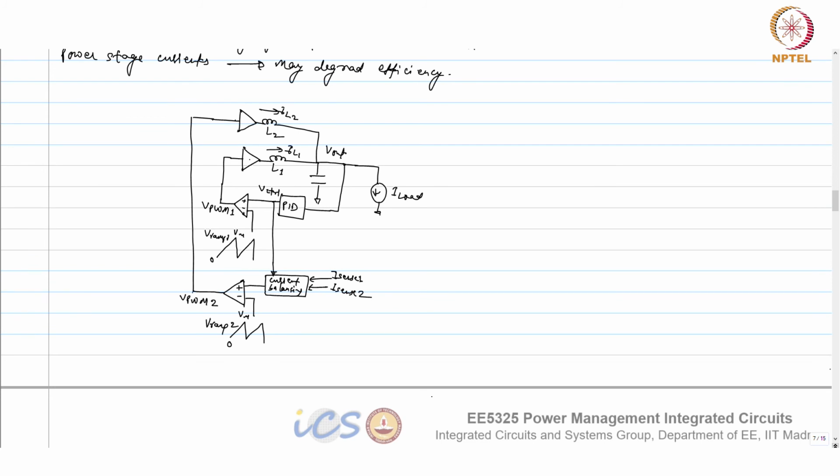So that's why, even if the inductor mismatch reduces your efficiency a little bit, you don't care, because that impact is not as high as a mismatch in duty cycle. But if you have a way where you can determine whether this mismatch is due to RDCR or due to duty cycle, and that is also quite possible, you can measure the duty cycle at the switch node. So you can always measure the duty cycle at these two, VSW1 here and here. Ultimately, you are interested in that end duty cycle, huh?